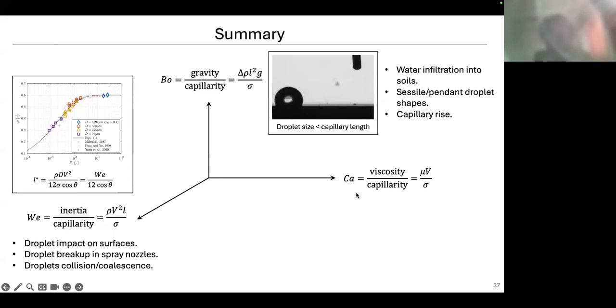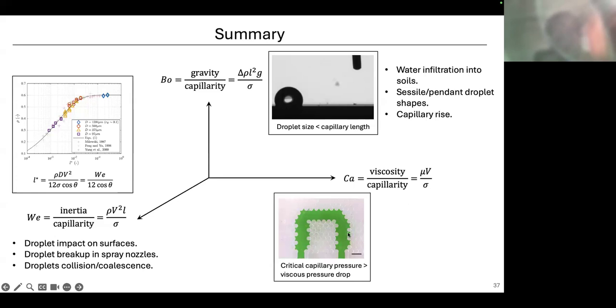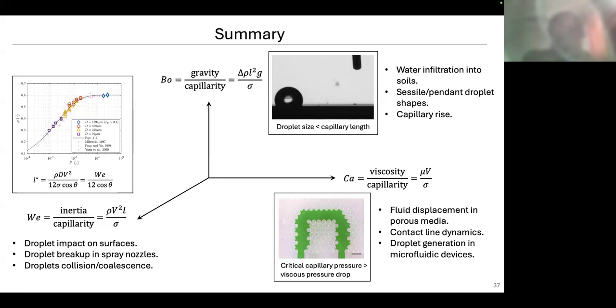Last axis, that's the capillary number, so it's a ratio of viscosity to the surface tension. In the very bottom case where we do the multi-phase flow microfluidic experiments, one important thing really is to ensure the capillary force dominates over the viscous pressure, so we need to ensure the injection rate is slow enough. Otherwise, if we inject very fast, it will expand more uniformly, more compactly, dominated by viscous forces. So that's a key parameter in the third case study.